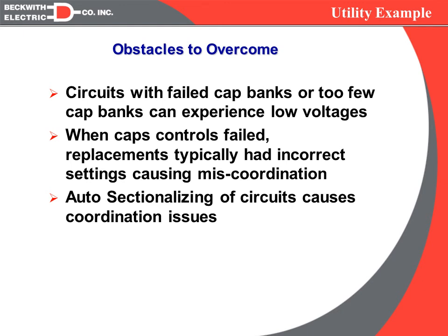The downside to that is when using a negative X, if you have lagging VAR flow, it actually induces the regulator to want to lower the voltage. So if you have a circuit with either too few capacitor banks or capacitor banks that have failed, then you risk having very low voltages at the end of your circuits. So there needs to be a way to coordinate that better with the negative X.